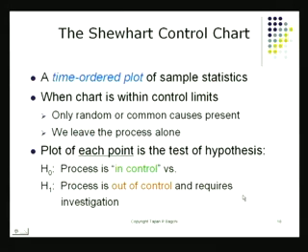So what is a control chart? It's a time ordered plot. And it provides you with a signal when there is no special cause impacting the process. Nothing has gone wrong, nothing profound has happened to the process, and the process remains within what we call an in control state. And of course, if some wild things happen in the process, like a tool breaks down, or the raw material is changed, or a new operator comes along and starts operating the machine, those are likely to cause some exceptional variations in the process. And the control chart may go then out of control.